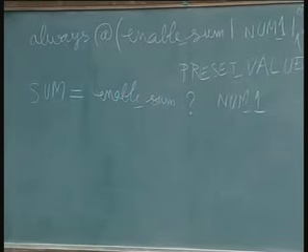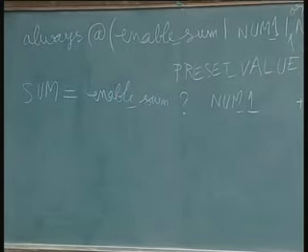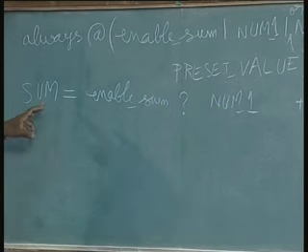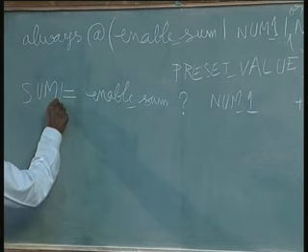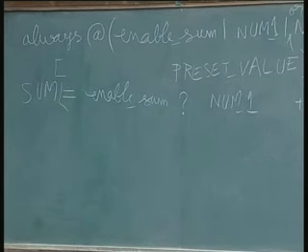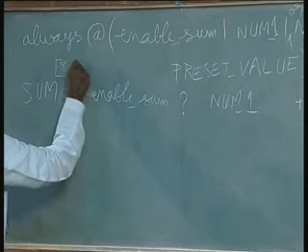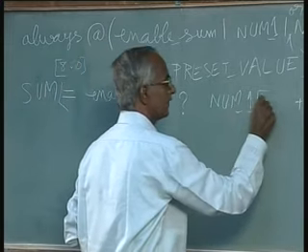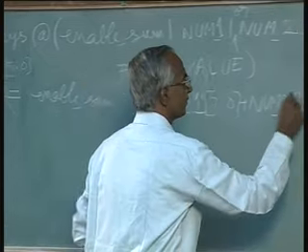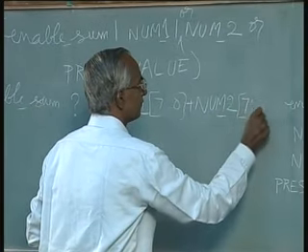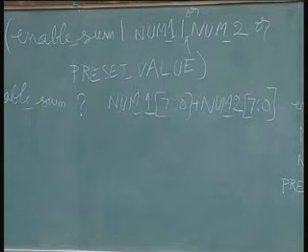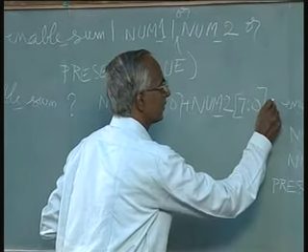Do you think this statement will work? We have not put the precision as such, it will still work, and we can also make the precision here, which is normally done by all designers, because we do not have to wade through previous codes and find out what precision it is. So, in this statement, we can identify that by just mentioning the range as such. Say for example, 7 to 0 and so on. Will this statement still work? It will not, because we have not terminated it with a semicolon here.